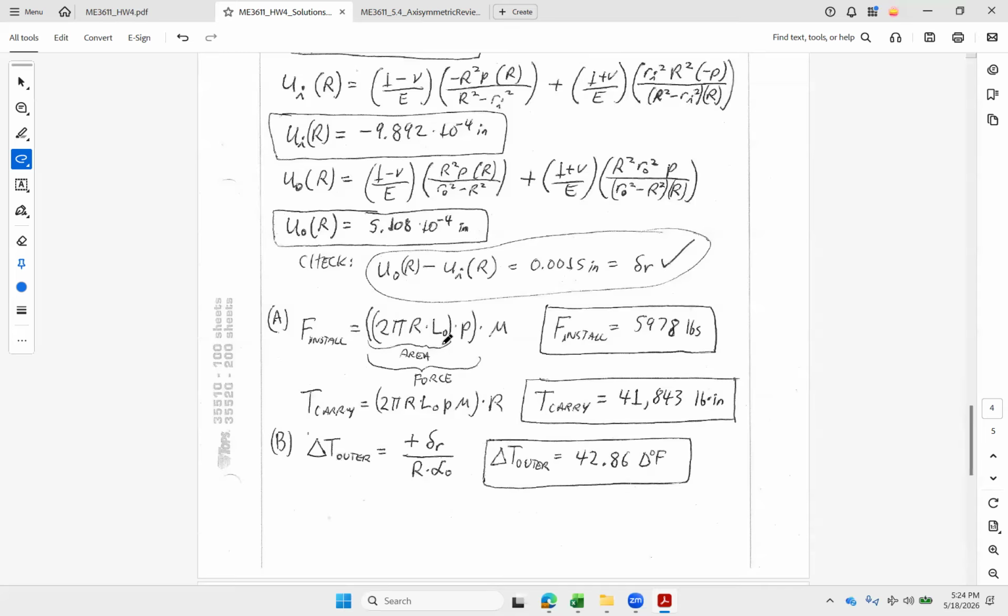Option 1, if we use the Triple H approach, we're going to have to install with about 6,000 pounds of force. All right, that's quite a bit of install force. We're going to have to open up a couple of the hatches, and he's going to have to jump from a few decks up and then land on the announcer's table. Right? But once it's on there, we can carry 41,000 inch-pounds of torque. That's way more than we need to run a fan. We could probably run some accessory generators off of something like that.